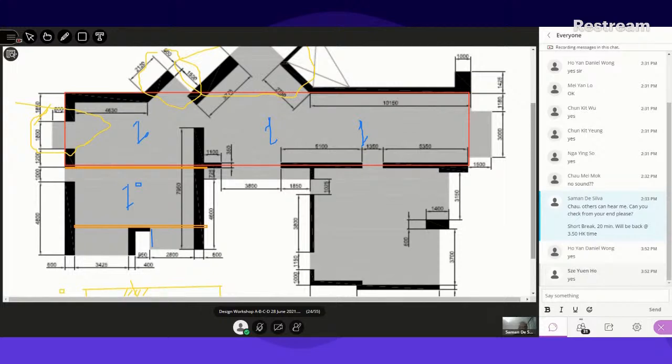You have to have a beam there, and then there's that one here, and then that one will be these two little segments coming to the edge. So you can have that being supported. If you wanted to go this way, it's okay. Otherwise, what you can do is a simply supported beam. A small segment of this slab comes and goes like that, because this is only 2.8 meters. You can deal with it easily.